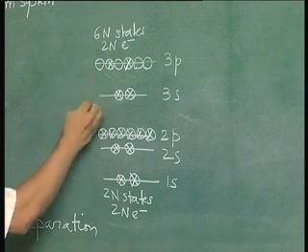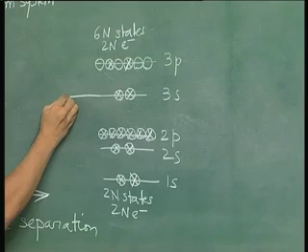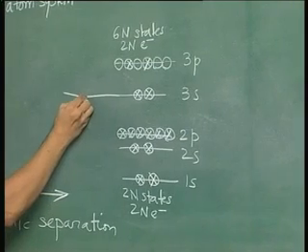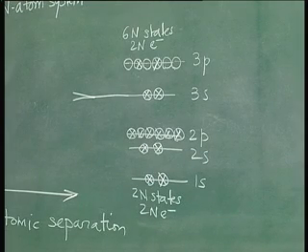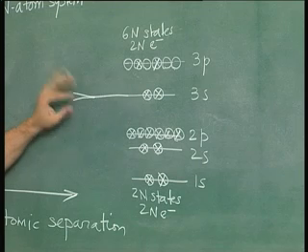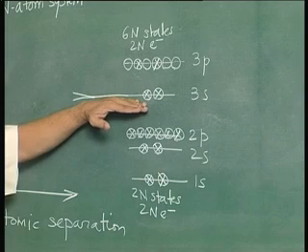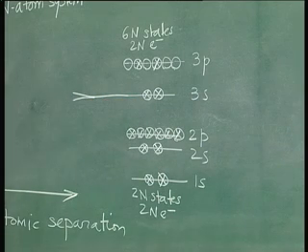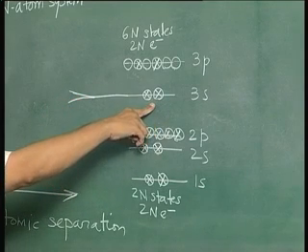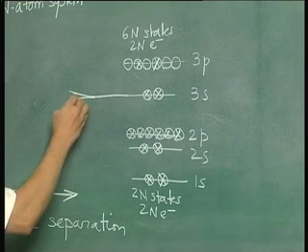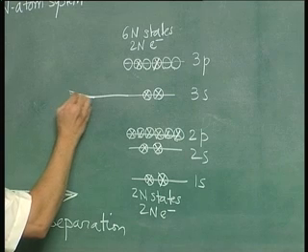As a result, this 3s state, as you bring the atoms closer, will tend to spread into a range of energies. That is what is shown here by the spreading of a single level into a band. Strictly speaking, in this band there are 2n states and 2n energies, so I should show 2n separate lines, something like this.